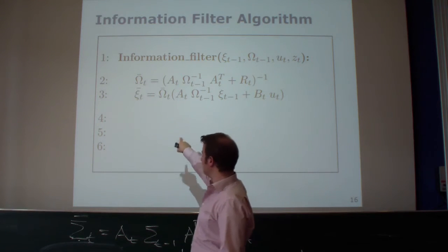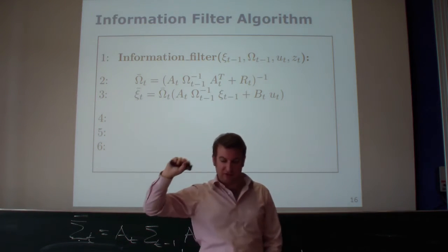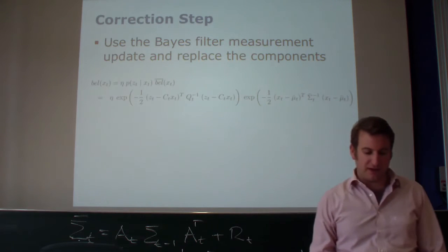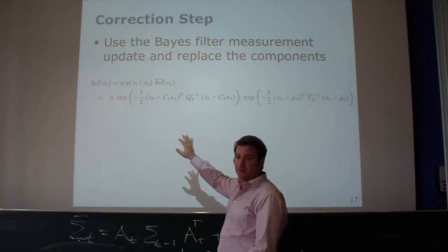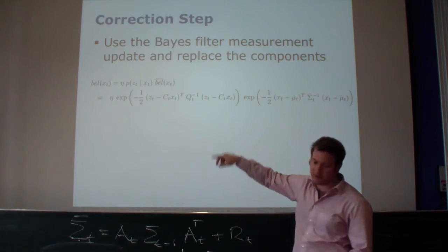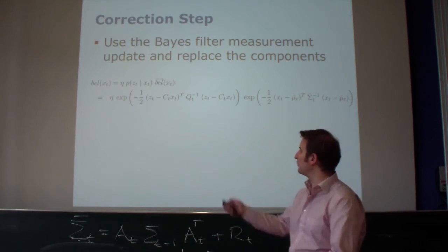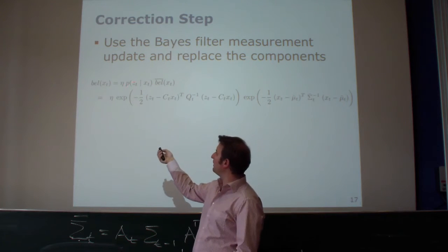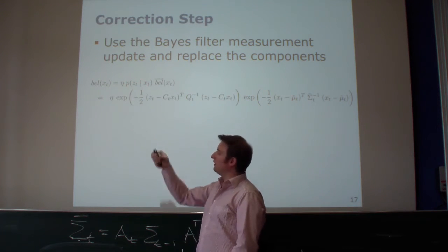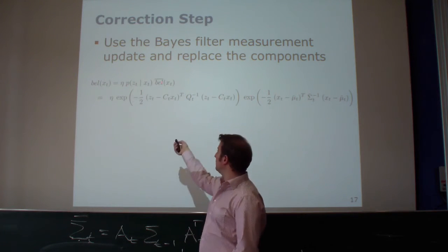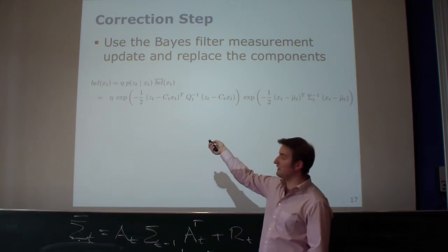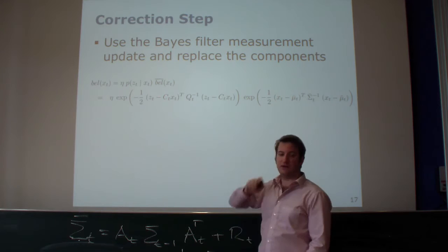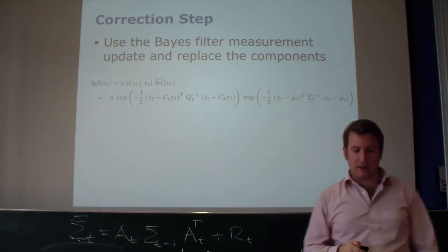It's more difficult if we manipulate all the matrices of the Kalman gain, so we can actually look that up in a similar way. If you look at the first Bayes filter equation, the Bayes filter was a normalization constant times the update step of the measurement model times the predicted belief. And this guy we already have. We know that's a Gaussian distribution.